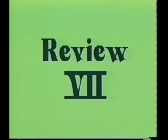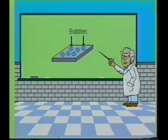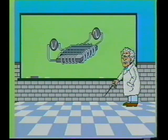We will now look at a brief review of our discussion of magnetic bubble memory devices. Bubble devices store data in the form of magnetic particles called bubbles which float in garnet material. The presence of a bubble indicates a 1, and the absence of a bubble indicates a 0. Bubble movement is controlled by two rotating magnetic fields that are perpendicular to one another, and each carries a sine or triangular wave current which is 90 degrees out of phase.